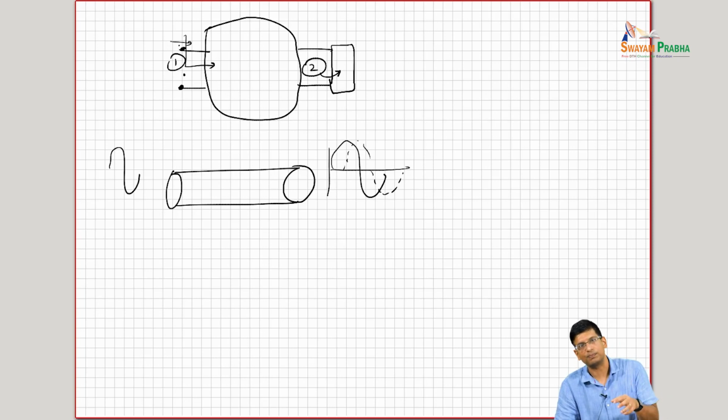So measuring S parameters, you can measure it without your network impacting it, right? So it's just a lot easier to measure S parameters in your system. So from a network perspective, we generally at high frequencies, and particularly because early on work at these frequencies happened with discrete devices, right? So you generally start describing them in S parameters.